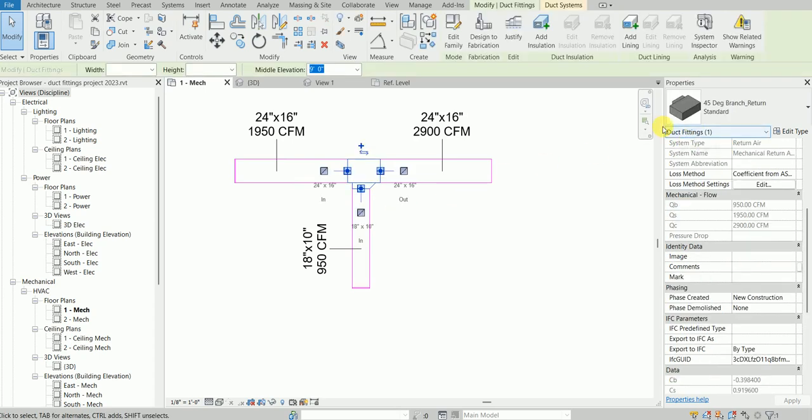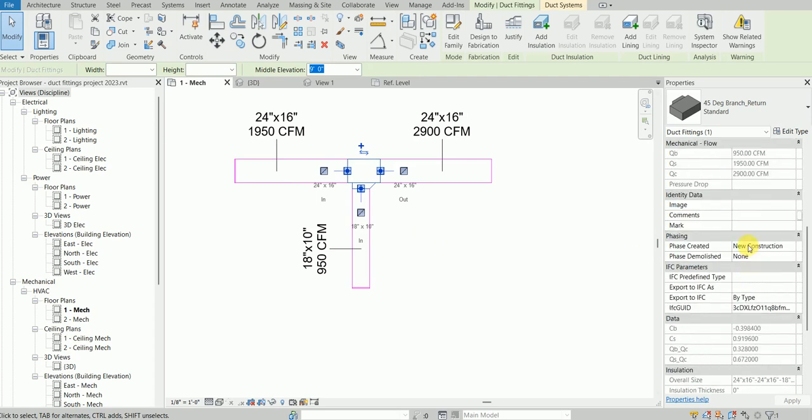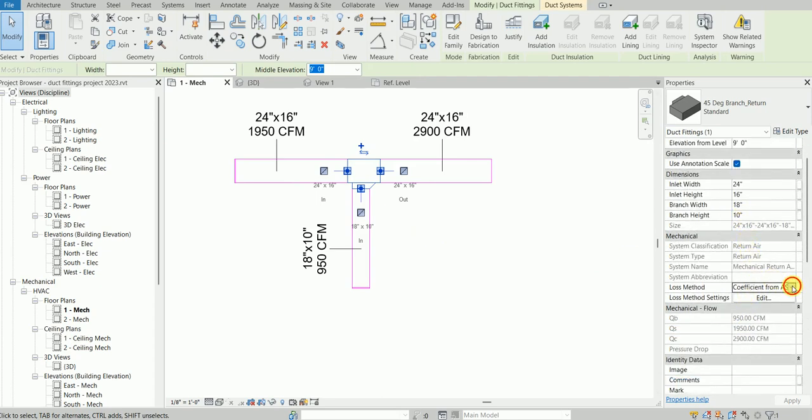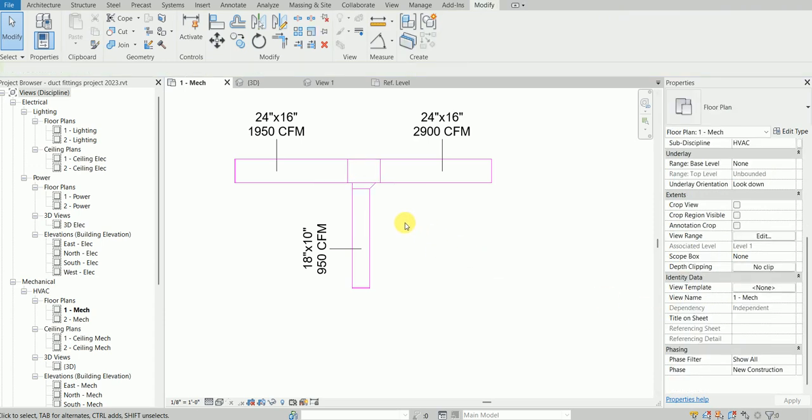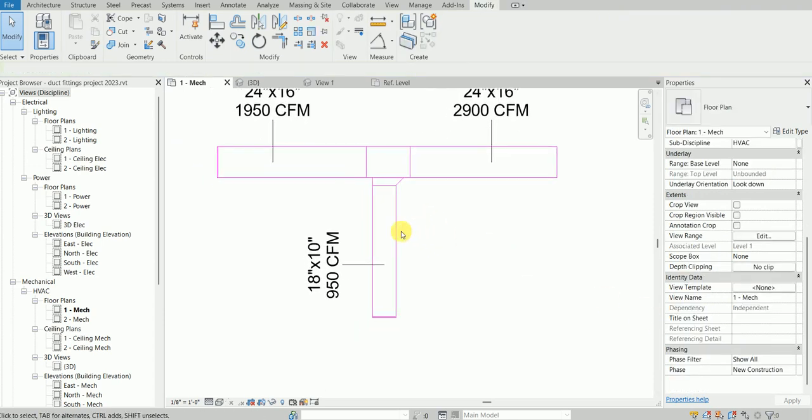So what I'm going to do now is also do the calculation, but before I do, I have to make certain changes. First of all, I have to select Not Defined from here, because I don't depend on this anymore. I don't depend on Revit to give me the correct or any ASHRAE table, because I'm doing all the calculation within the family.